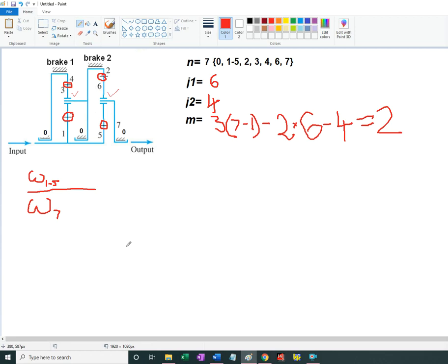Since I'm dealing with 2 units, I would need to do motion inversion. I'm going to write a second equation, also motion inversion, that relates the RPM of number 2, which is the same as the carrier. But since I use omega 7, I would need to work with this second unit, subtracting omega 7 from the 2.